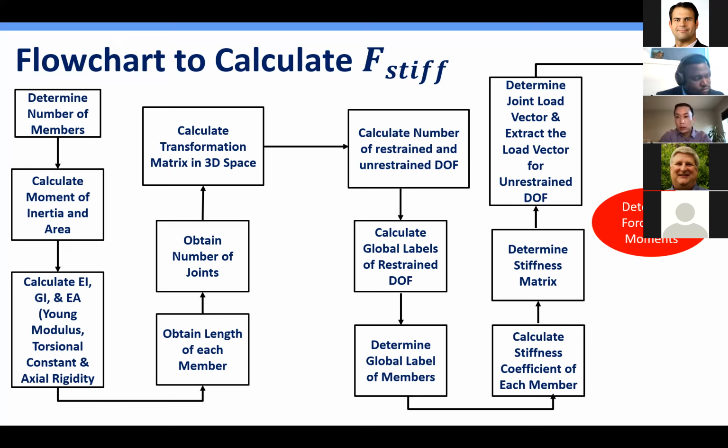Okay, thank you. Along that line, when we've looked at stiff string modeling, we've used commercial stiff string models that are available, and it seems, number one, if you don't have anything but 90-foot surveys, so if you don't have higher resolution survey data, you don't get enough detail in the wellbore to really have much of an effect. That's rule number one. It seems I need 3-foot spacing on survey data or better. The other, and I think many people have said this as well, is you don't tend to see stiff string effects in the drill pipe. Much more so in the BHA.